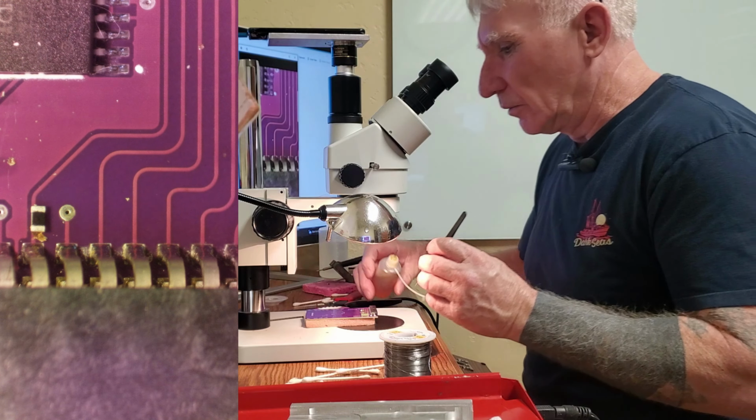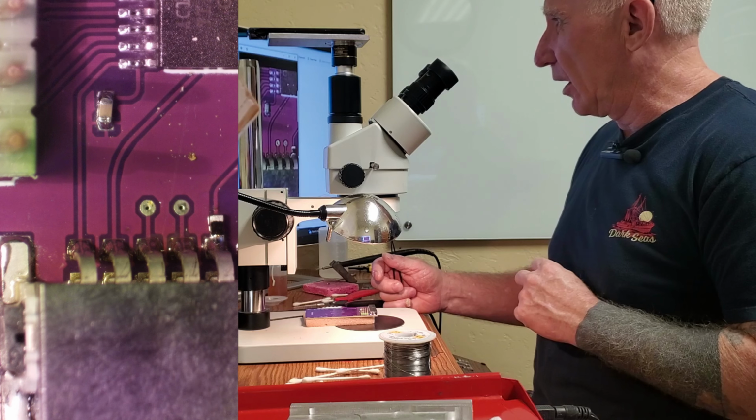All right, so see if I can hold this thing down while I solder it. And there we go. That puppy's soldered. So 1, 2, 3, 4, pin 5. All right. Now we got to get a wire on there. Let's move this down a little more because we have to be able to see pin 1, VDD, and the resistor at the same time.